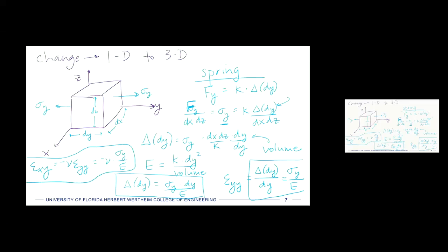And then we can do the same thing for zy. Okay? And the letter that we're using for Poisson ratio is the Greek letter nu. It is not a V, but it's a wavy V, so it's a nu. Okay, so we can do this for all three directions. And then we're getting there to what Hooke's law is, but we're not quite there yet. Okay, so let's do a little bit more manipulation with these values.